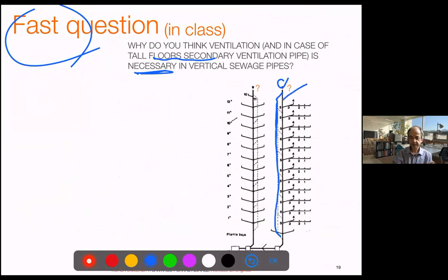Actually, vertical pipes are between 10 and 15 centimeters in diameter. The parallel depends on the height. So it should be at least 35 millimeters. Can be the same diameter, but depending on the height, you make it bigger or smaller. Right?